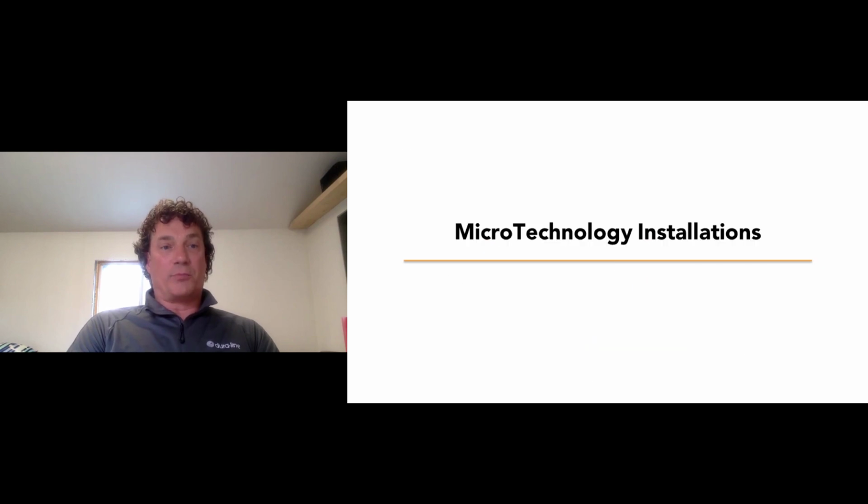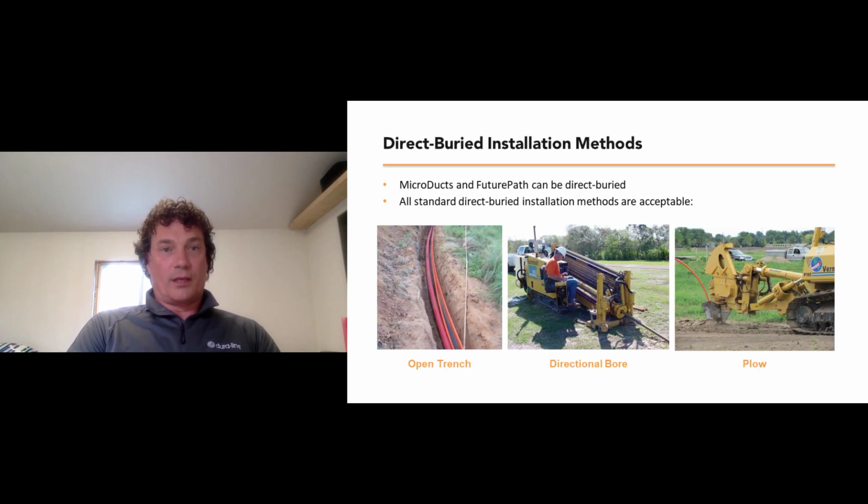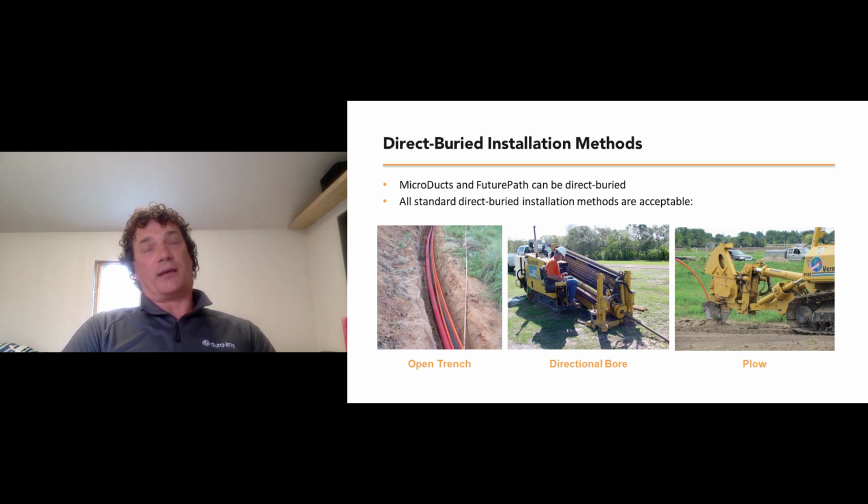So, the installation portion. To install the microducts themselves, a bunch of different traditional methods can be used. You can open trench it, you can directional bore or directional drill, or plow them in. There are other methods like micro trenching, which we'll also talk about.